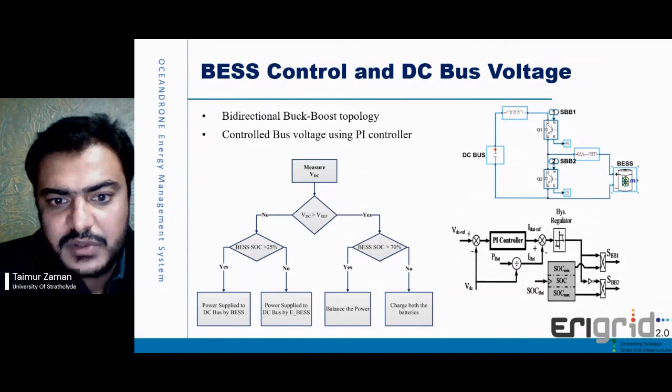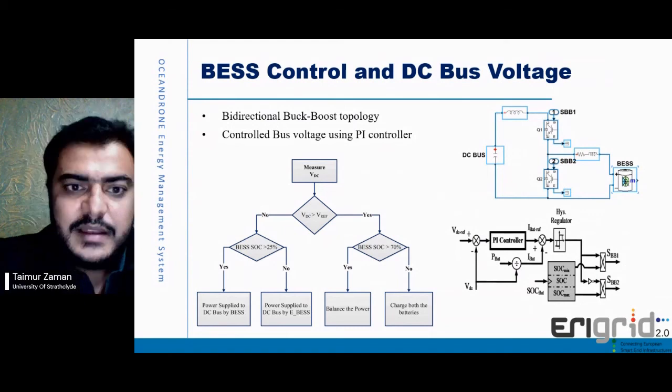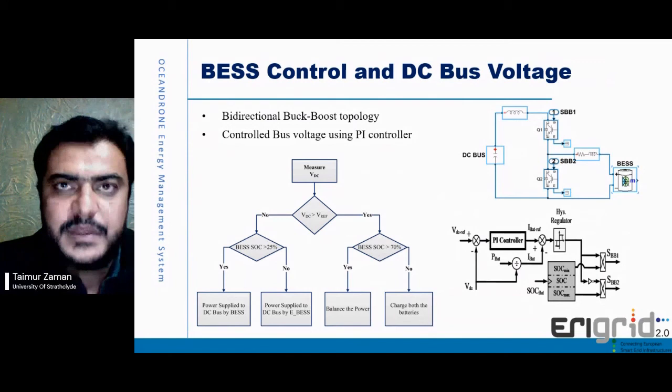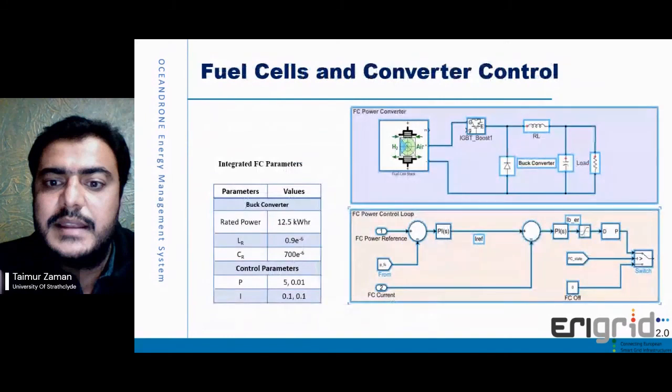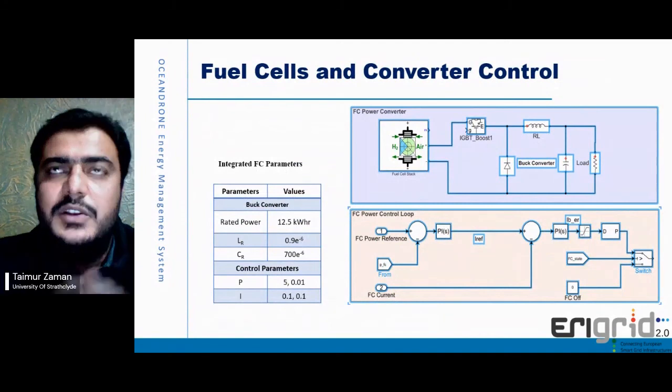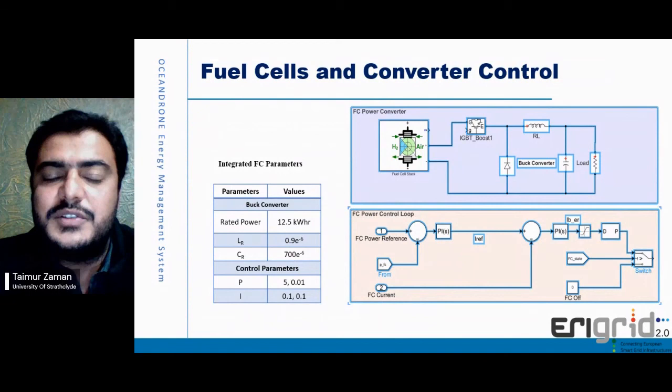Similarly, on the other side, if the SOC is less than 25%, the overall bus of 48 volts is maintained against fluctuation by another emergency BSS that has been included in the architecture. Apart from this, it is to include redundancy in the system of the offshore drone, because it has to go on missions for 24 hours or so.